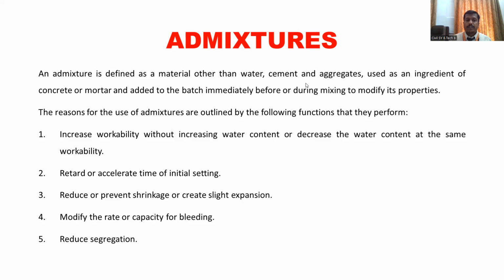Okay. The reasons for the use of admixtures are outlined by the following functions that they perform. What do these admixtures do? Admixtures will help us to increase the workability without increasing or decreasing the water content. We can increase the workability of the concrete by the use of admixtures. Next, with the help of admixtures, we can retard, that is, slow down, or we can accelerate the initial setting time of the concrete.